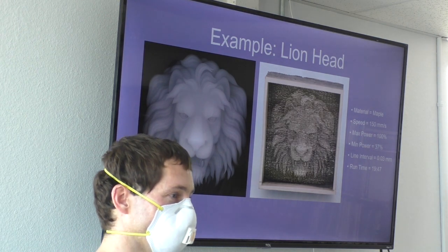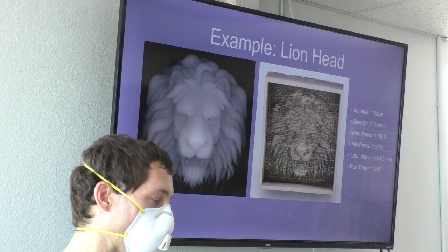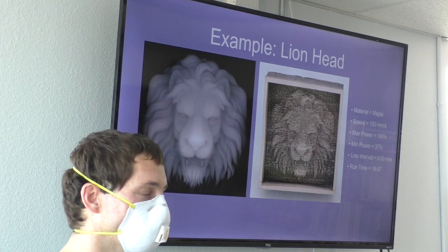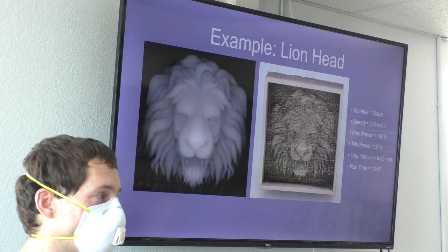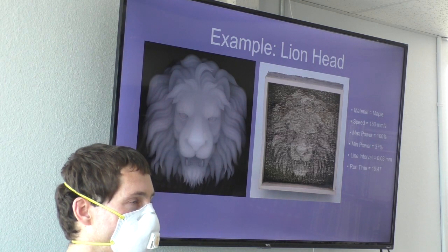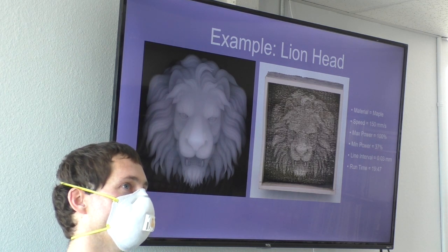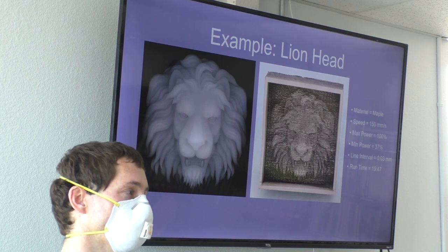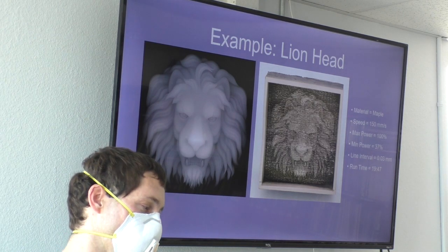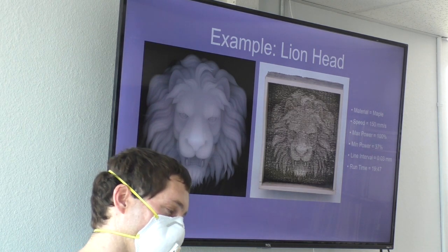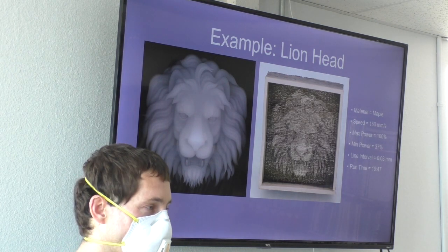I mean, you're right, from the optics of it, as you leave the focal point your power is getting spread out, dispersed over a wider area. But did you guys see this? That is just incredible, because that doesn't show it. So I think what's happening with the lens we have, and the laser itself, is that it has an incredibly intense power distribution in the center that gets much diminished as it spreads out. So even though the beam itself is spreading, the part that's actually the hottest is right in the middle, so there's very little spreading at all. So it's able to cut through the 3/4 inch maple without a problem.